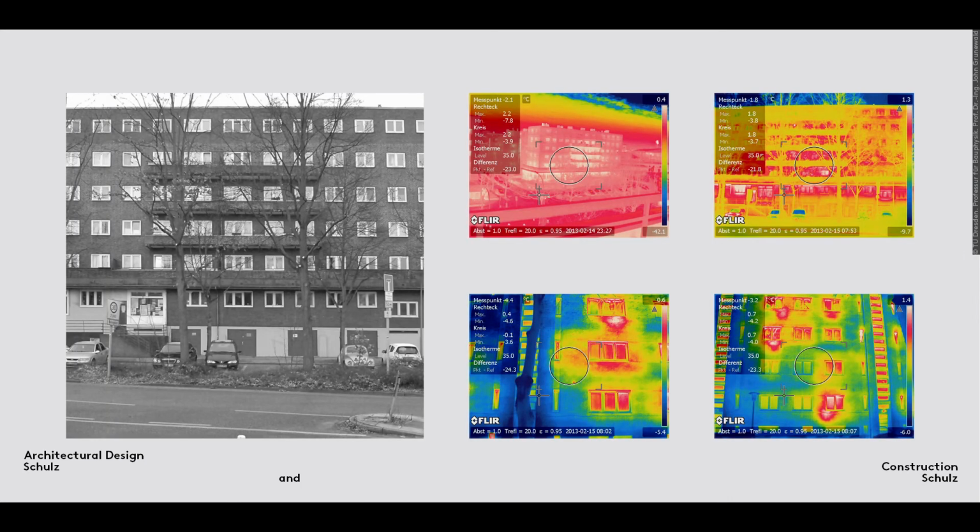Imagine a building constructed with 49 cm thick walls of vertically perforated blocks to ensure that the building shell provides a good level of heat insulation. Even this well-designed construction will have some weak points in the form of thermal bridges or areas of discontinuity where greater heat penetration occurs. This photograph, taken using a thermal imaging camera, shows thermal transmittance in a monolithic facade. The red patches show areas where more heat passes through the fabric of the building to the outside, the blue patches those where heat penetration is lower.